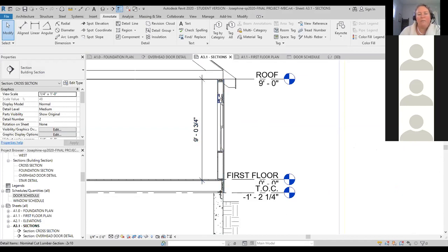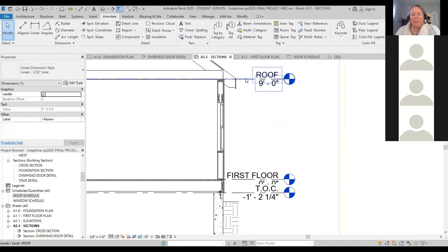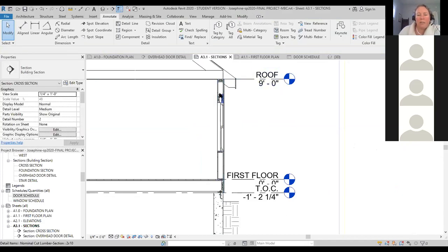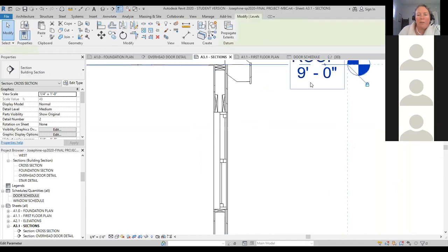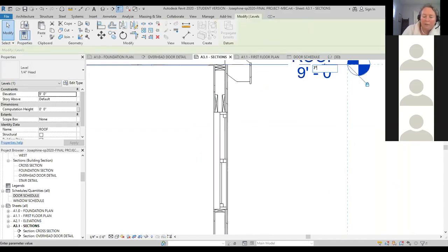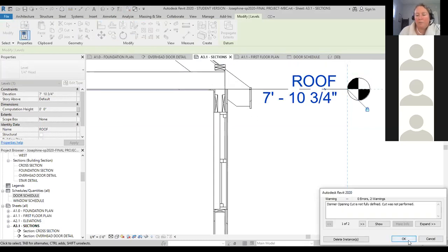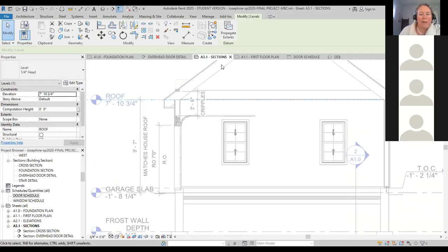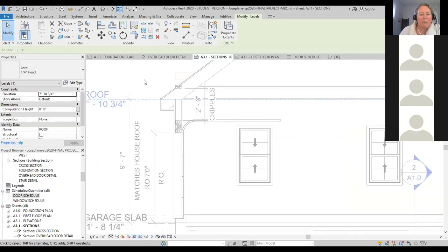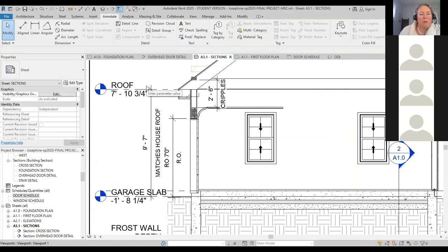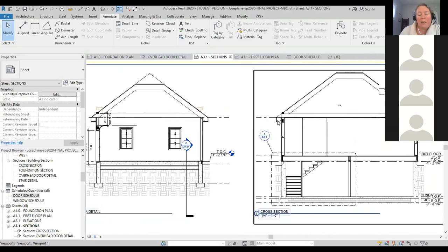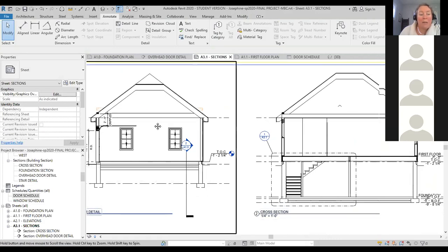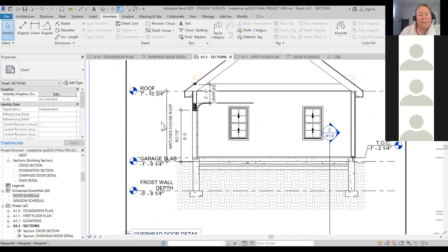the cripple height here. But let's see what happens if I drop this wall height all the way down to the lowest it can go. And I can do that by clicking on this and putting in that number of my minimum wall height. And if I do that, I'm going to just ignore the warnings it gives me. Now because I have my garage wall or roof locked to the same dimension, our new dimension for our wall height over here, at a minimum, if we wanted it to be coordinated with the main house, this wall height in the garage would have to be 9 feet 7 inches.